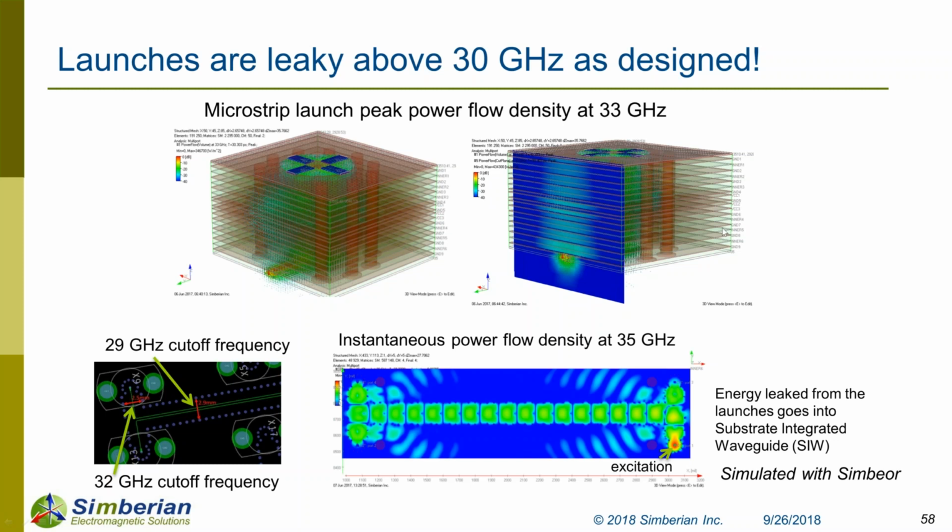So in the end, we can say about predictable interconnects that it really comes down to decomposition analysis. You have to be able to simulate each block in isolation, because otherwise it's computationally prohibitive to simulate the whole link. Let's say you have a 15 inch long trace and you want to do everything in 3D solver, it's not possible. You're going to run into numerical problems and it's not going to converge. So you have to rely on decomposition analysis, and for that to be valid, you have to be able to simulate all the discontinuities in isolation. So localization basically means everything in this case.